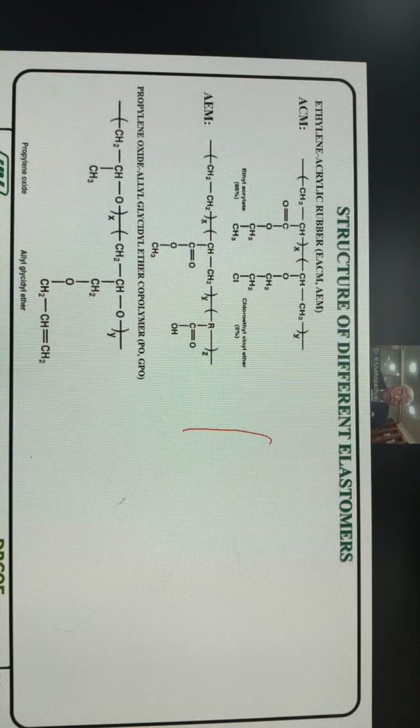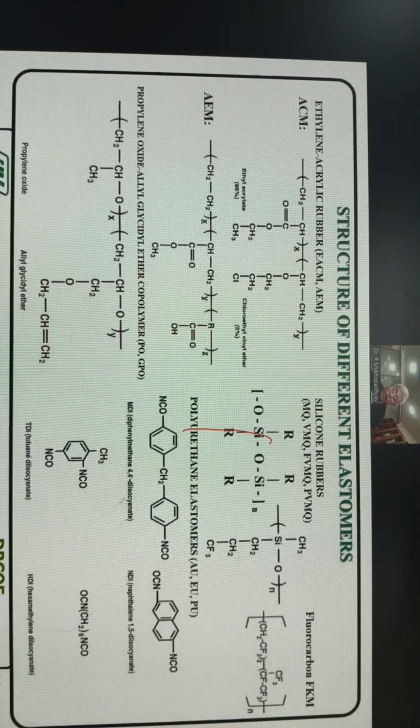Similarly, if you see the other specialty rubbers, especially non-tire, with the arrival of electric vehicles and others, auto rubber components will also become specialty, and more and more specialty rubbers will come into the picture. I will try to explain in subsequent slides how to select which type of polymer for which type of product. Now, last but not least are the polymers for high temperature use, especially silicone or fluorocarbon. All those applications really require fluorocarbon or silicone.